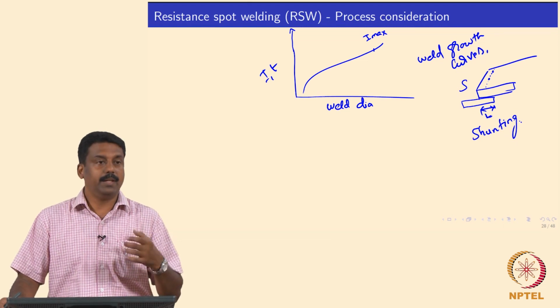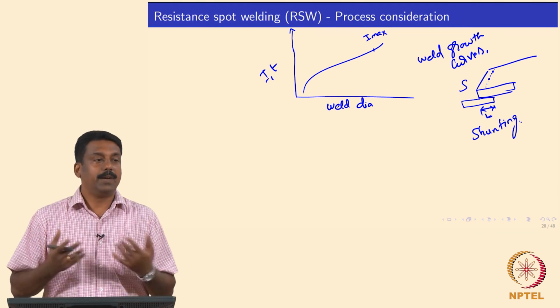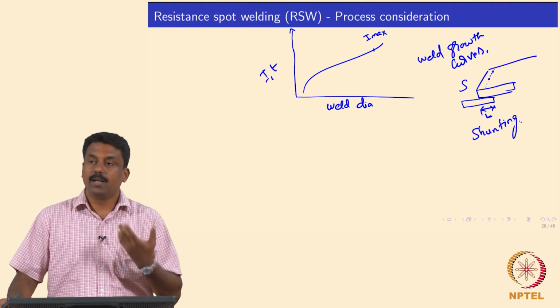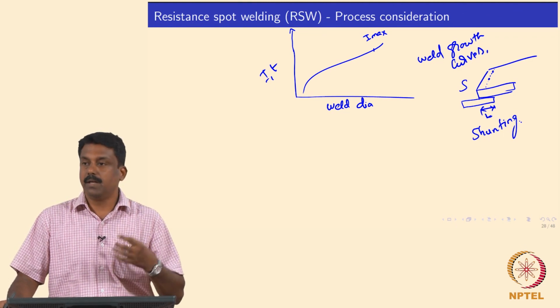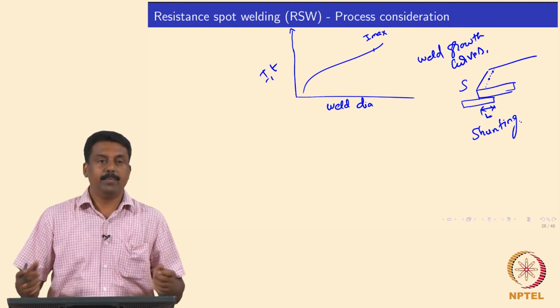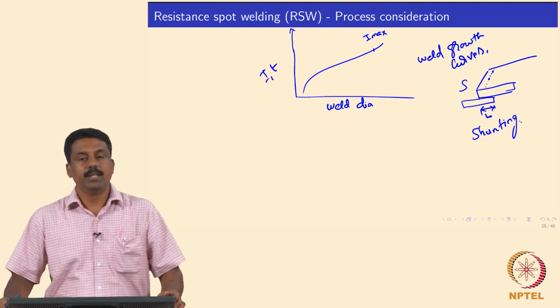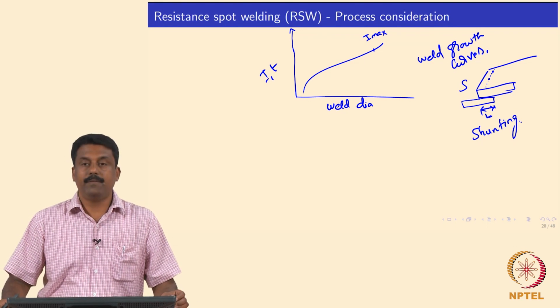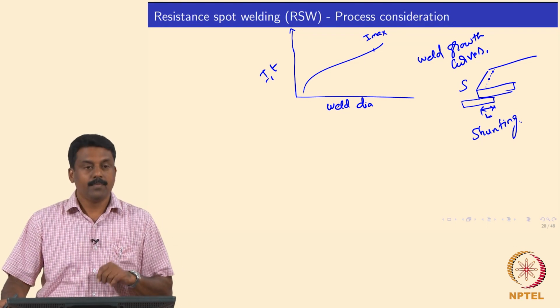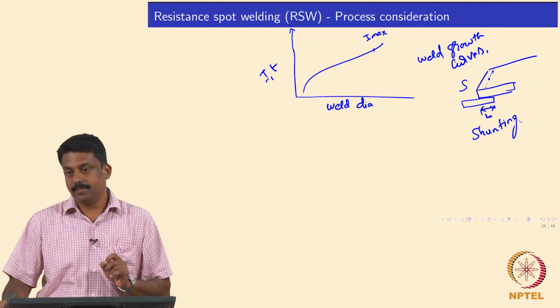The distance between two welds is also critical in terms of structural stability, right. When the design is considered for an automotive industry, they look at detailed structural analysis, okay, to see how the member behaves under static and dynamic load, and they do a stress analysis to identify where exactly they can place the weld, considering the shunting effect, okay.